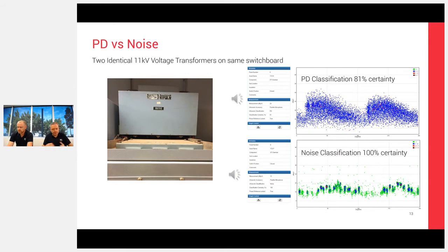If it's completely random and it's just appearing across the screen very quickly, and you're not seeing any drift left to right, right to left, then that is a genuine noise type source. So you will see some noise sources ultrasonically where it is just flat across the screen from almost the moment that you take the measurement. If you're seeing the drifting, then you have got a phase lock. You can manually adjust and you can still achieve these two things here.